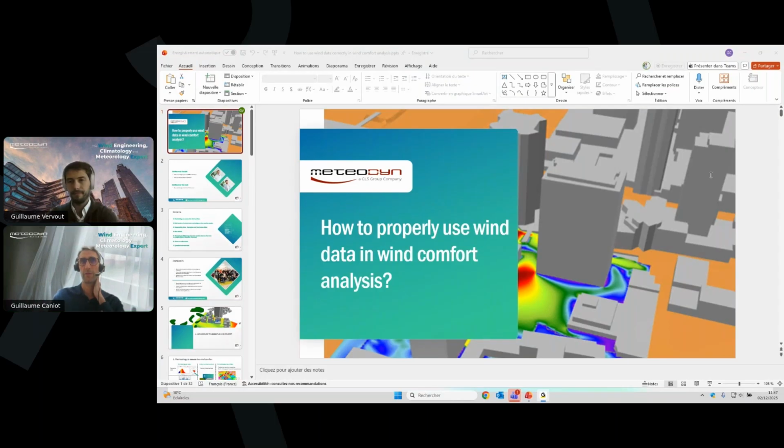So if your reference wind speed is at 150 meters, this is the limit, I would say. Otherwise, you need to use the log law from this 150 meter height to go a little bit higher. Otherwise, it's potentially affected.